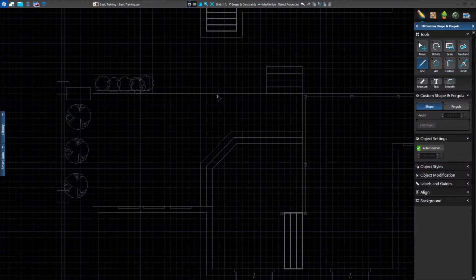Using our line tool, we'll first create the overall shape of the kitchen we plan to build. We'll draw 20 feet left, 12 feet down, 3 feet right, 9 feet up, 17 feet right, and finally 3 feet up, or double-click on the last point with the Auto-Complete target present to complete the shape.